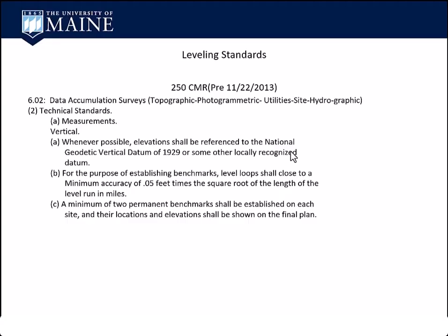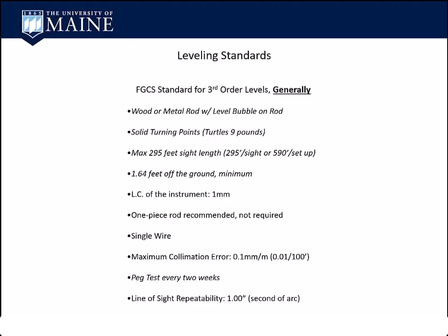So you can't meet a specification like this without running levels and capturing the distance of the backsights and foresights. You can't run a single level and meet this. It's kind of outdated anyways, but if that's the spec, that's the spec.